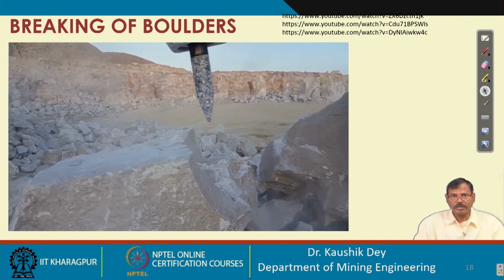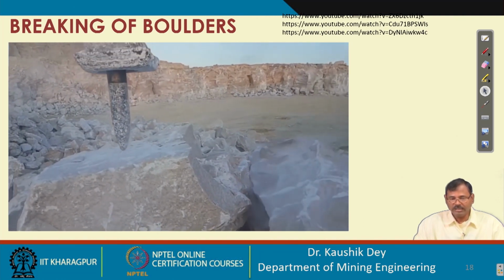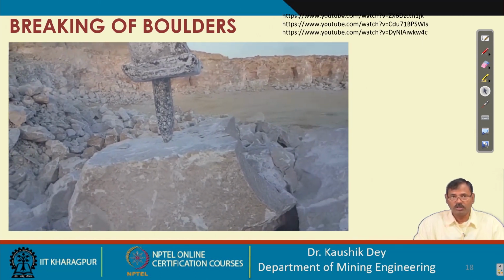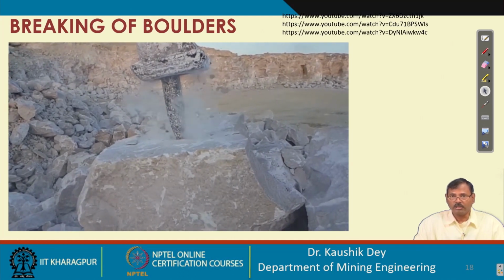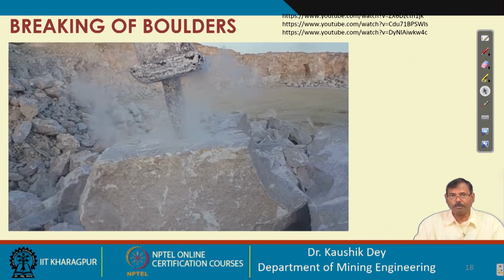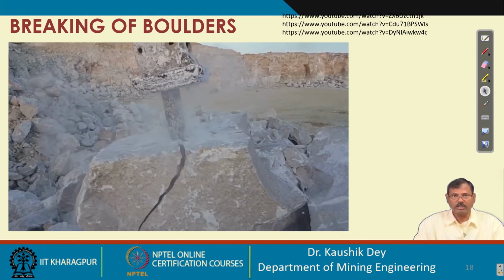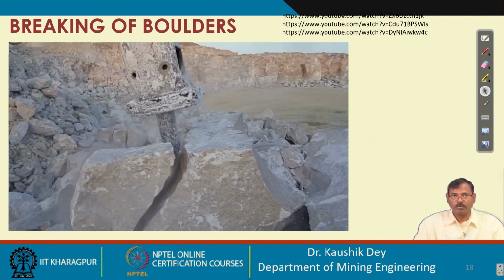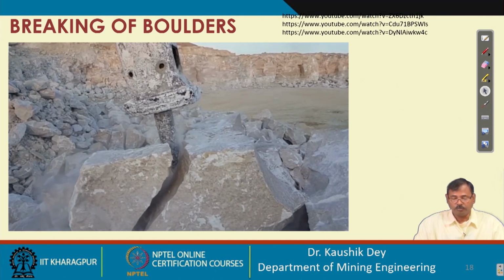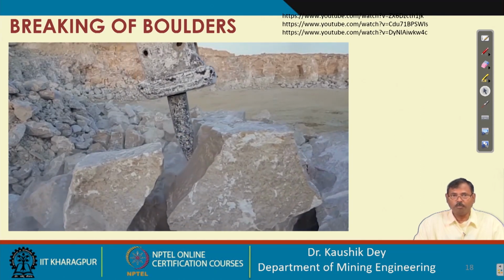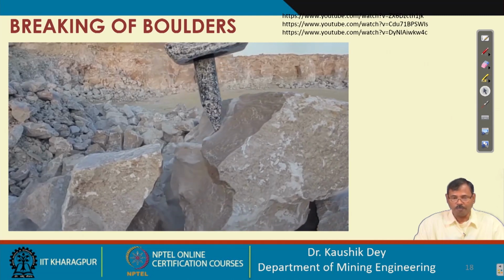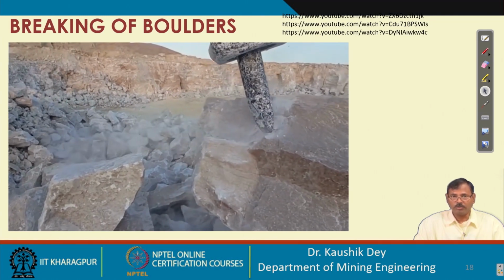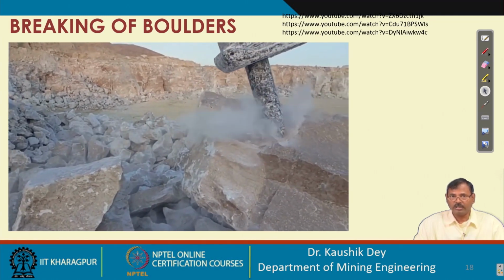These pneumatically operated hammers can be easily placed in an excavator boom within half an hour, replacing the bucket, and this method is very easy. Any problems associated with the blasting process can be avoided by using this mechanical hammer system. These hammers are not very costly, depending on the hammering strength required.